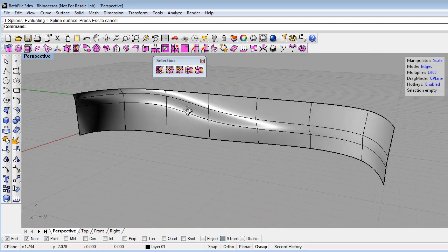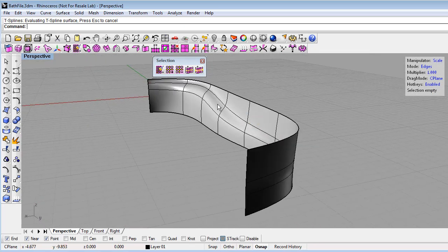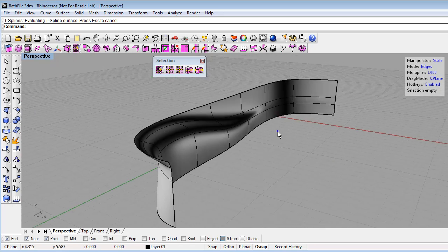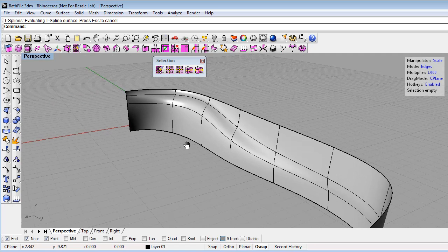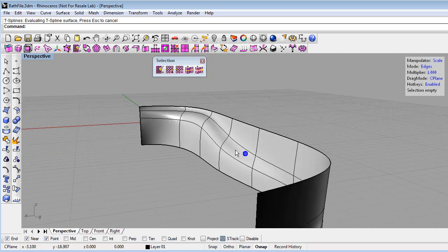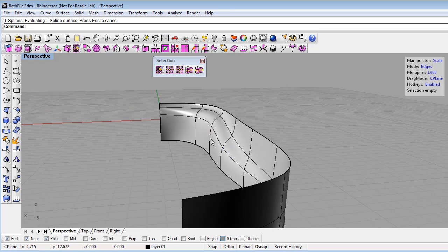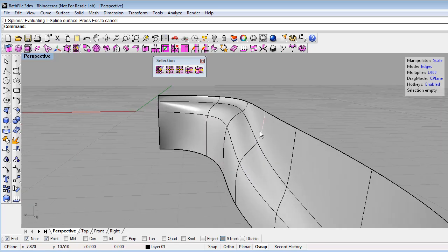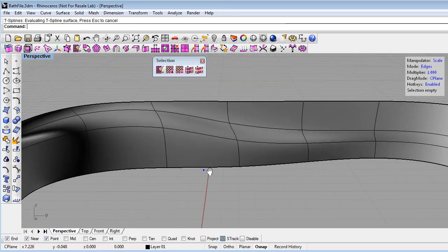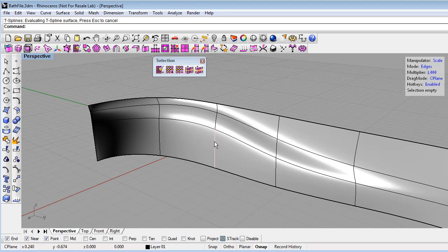So now I have merged this into one single smooth T-spline, and by merging those and making it smooth, I actually washed out a decent amount of the detail that I had before. Because remember, this used to meet at right angles, and now since there's not very many control points, it's really kind of washed out that detail. So I'd like to add some definition back in here, kind of tighten up these angles. And the way to add more definition or a tighter curve to a T-spline model is by just adding more control points, because the closer the control points are, the tighter the surface will be.